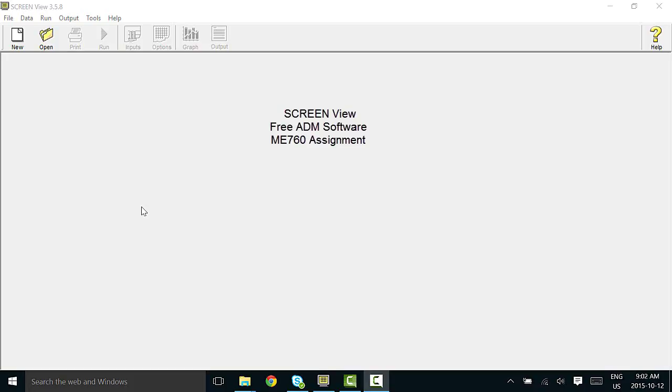This is part of the assignment for the course ME 760 at the University of Waterloo. We are covering mobile sources air toxics risk assessment. The segment for this lecture refers to air dispersion modeling, and I want you to practice using a simple program like Screen View and change stability classes and see what is the impact in the concentrations.